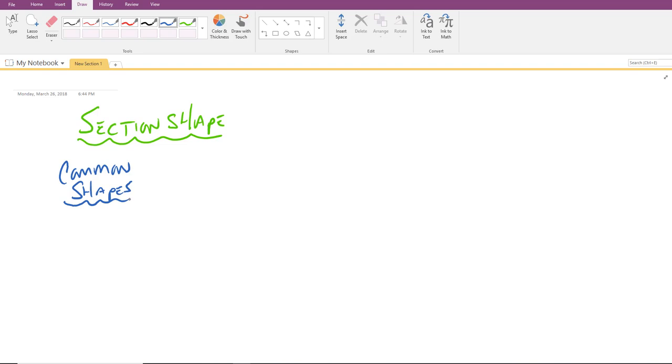Think real quick, what would be the cross-sectional shape of a steel column that you may have seen? Typical answers that I get from students when asked this question in class are circular. Usually they're hollow. We call those pipe piles. Also, sometimes they come in square columns, but they're also hollow, or we'd also say nearly square, and also wide flange shapes. Notice here that I'm drawing this more as an H as opposed to an I.